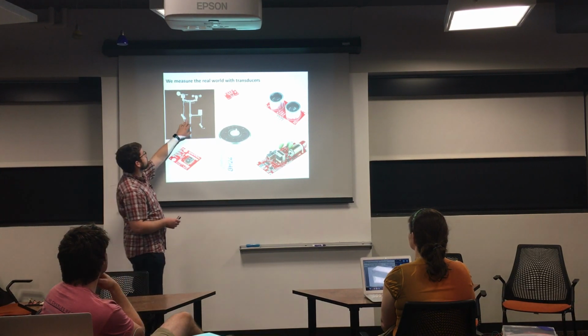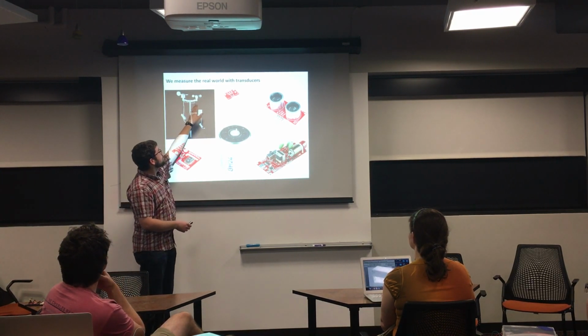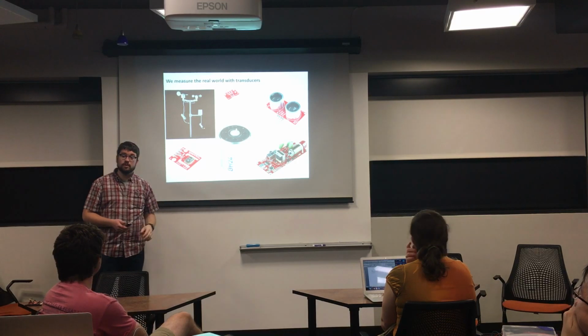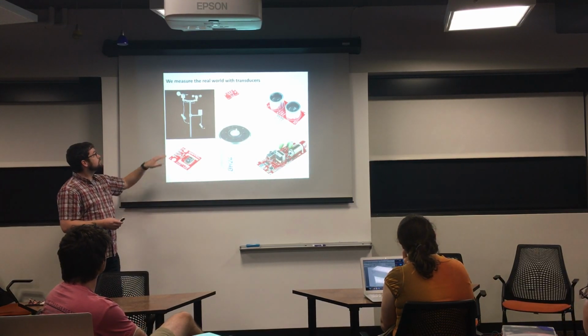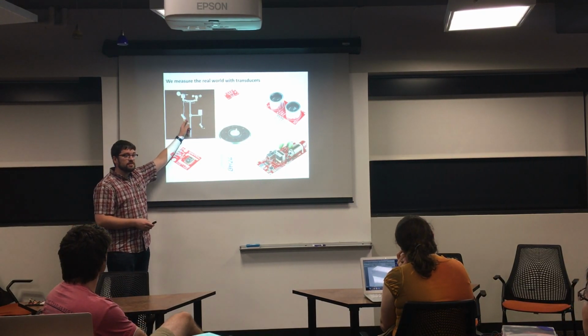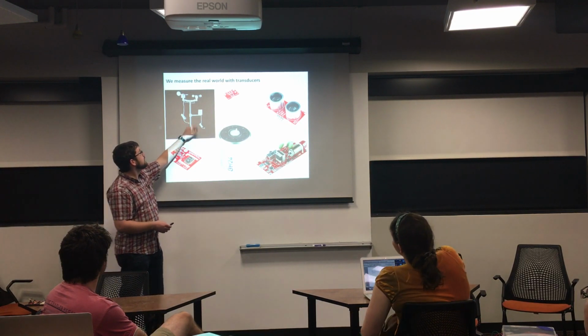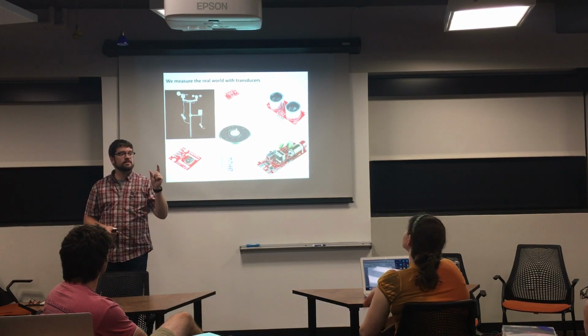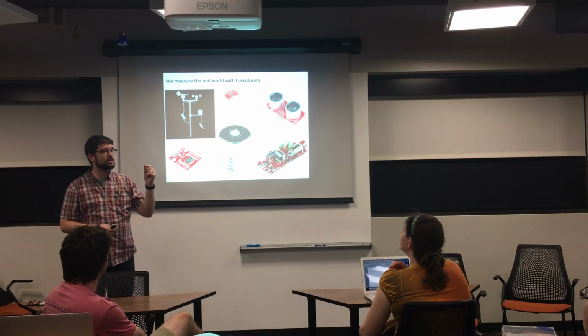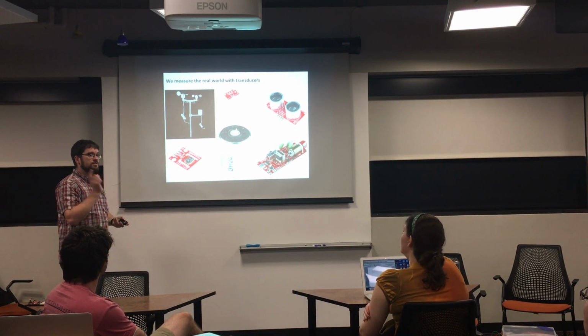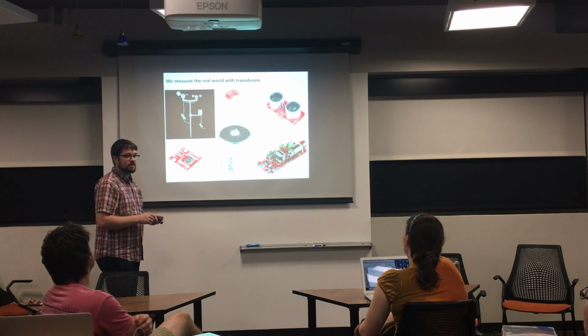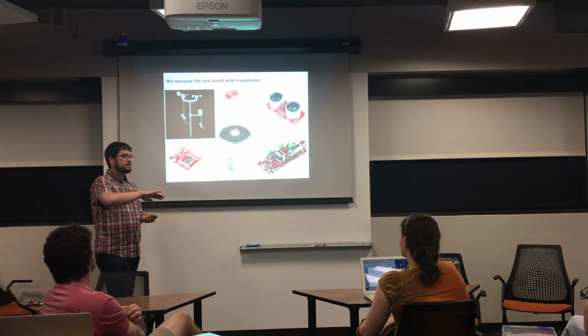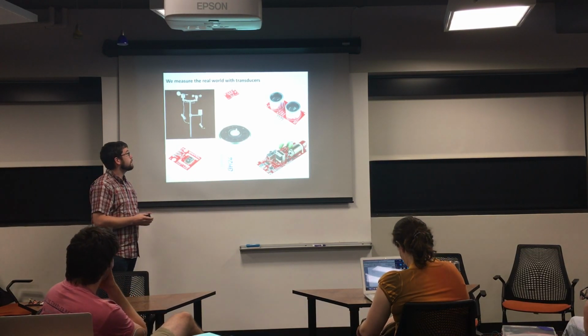So up here we've got a weather station. It's got wind direction, wind speed, and rain amount. The wind direction sensor would put out something like a resistivity change, and the wind speed and rain sensors actually just put out pulses. They just close a switch. So you count how many pulses per second, and that gives you an idea of how fast the wind is, or how many pulses the rain gauge puts out tells you how much it's rained.